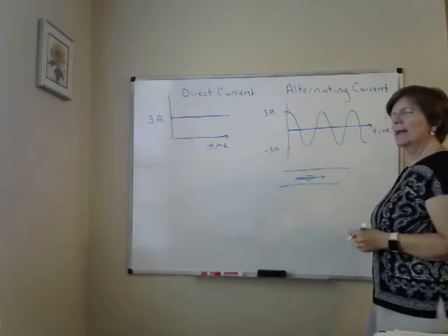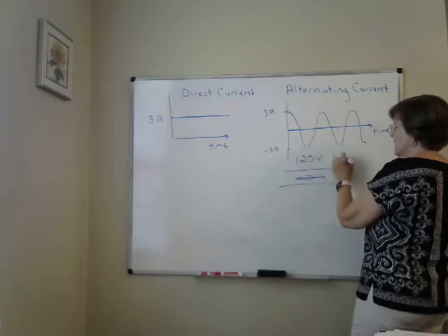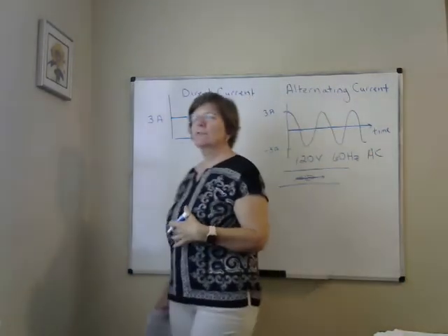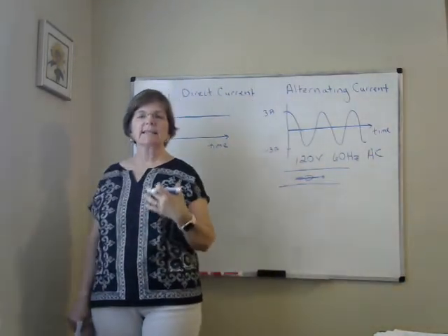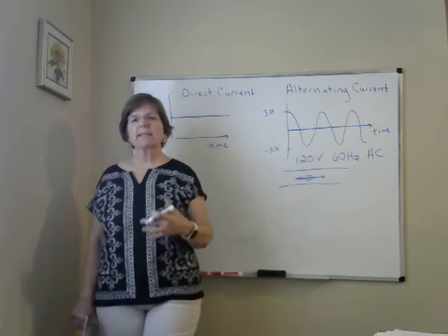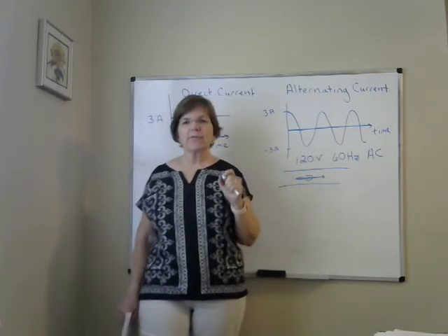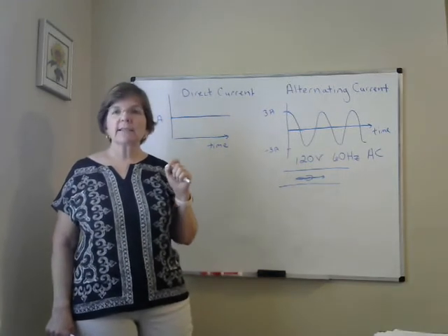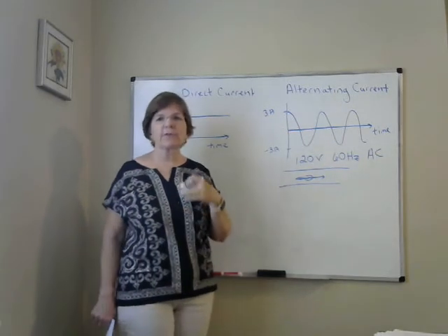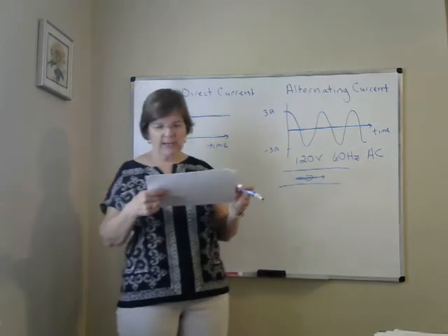They're vibrating. In fact, the frequency in the US, we use 120 volt, 60 hertz AC, alternating current. 60 hertz means that electron completes 60 cycles every second. It's doing 60 cycles every second. It's changing its direction 120 times per second. So those electrons aren't so much flowing as they are vibrating back and forth. Still does the trick. Still lights up our lights. And these periods where the current is 0 are so brief you don't ever notice the lights going out. Okay? So that's alternating current.